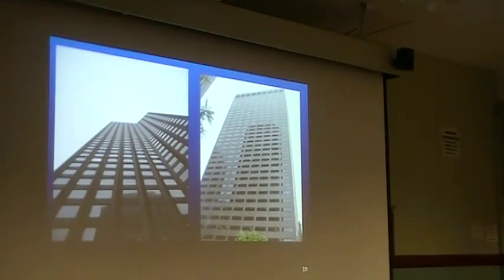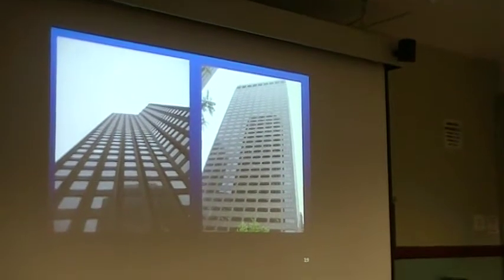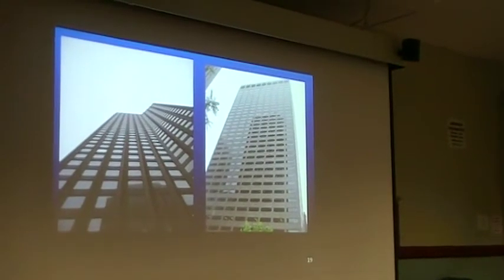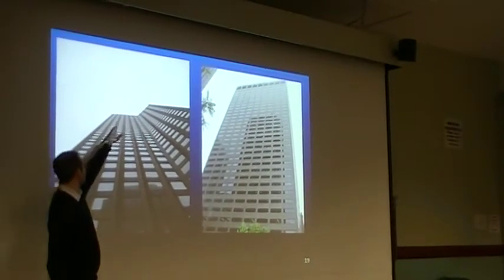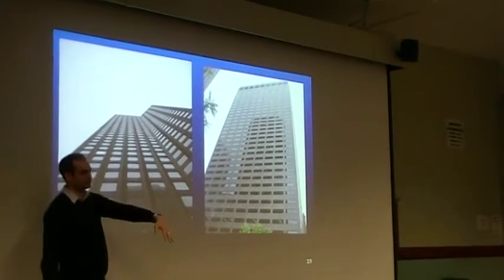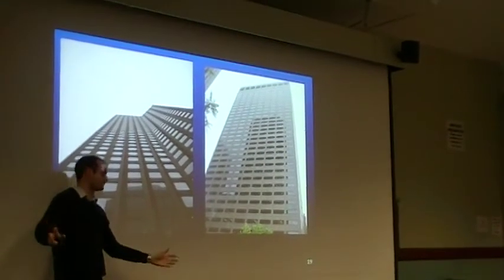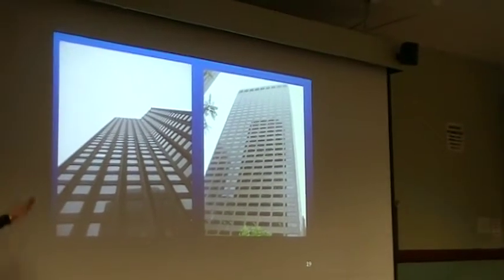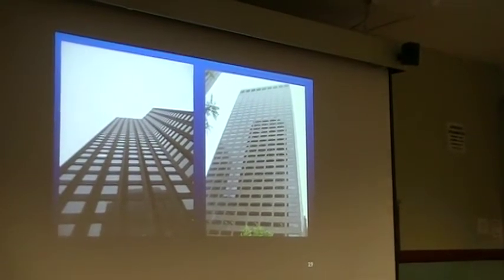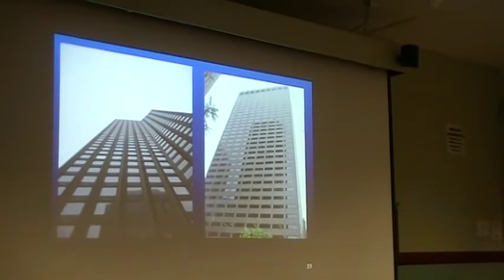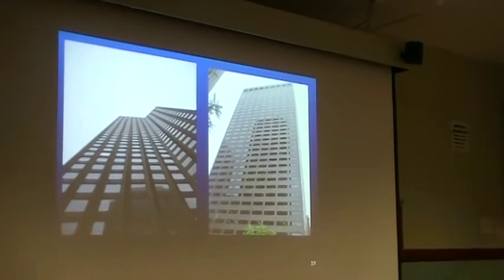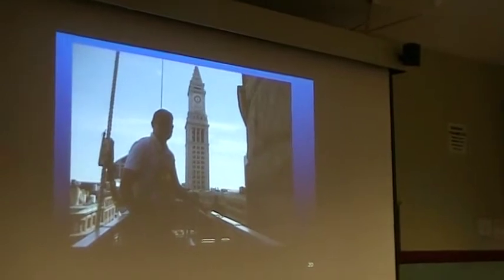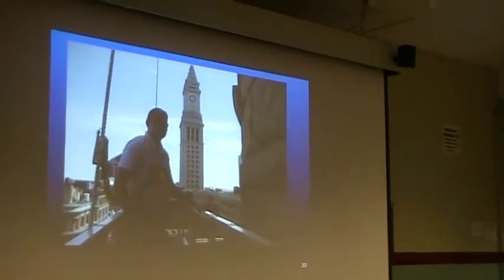Structural engineering, you work on facades. The problem with facades is they're full of stones. Stones are heavy, they eventually fall off. Who's ever going to know that there's this cracked stone up here until it falls off and almost hits a baby carriage? True story. One of the reasons why some larger cities have laws: somebody's got to dangle off the side of the building and at least look at the facade to see if there's a crack. I wasn't the guy on the rope. I was the goon on the ground. I've gone in swing stages looking for cracks, though. Structural engineering can be fun.